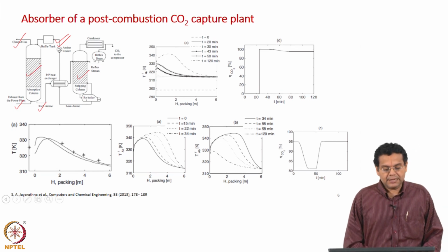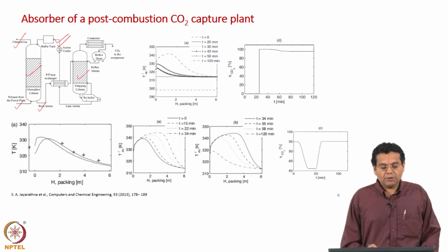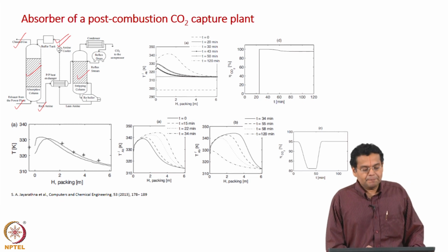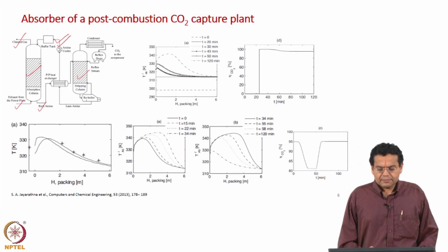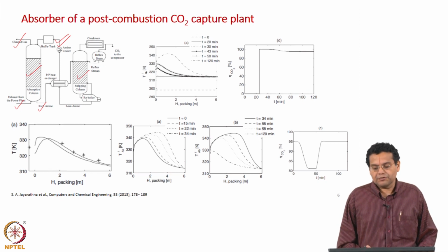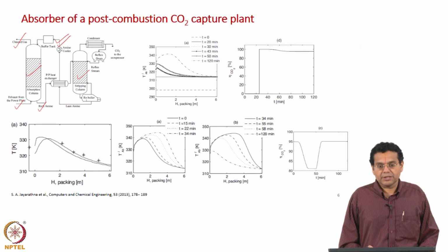In the present study, let us say we want to predict the performance of the absorption column. What do we mean by that? Let us say we want to predict the percentage removal of CO2 or we want to design this absorption column for the best removal of CO2, then we need to solve the conservation equations. What are the conservation equations? The energy balance equation and the species balance equation. So,